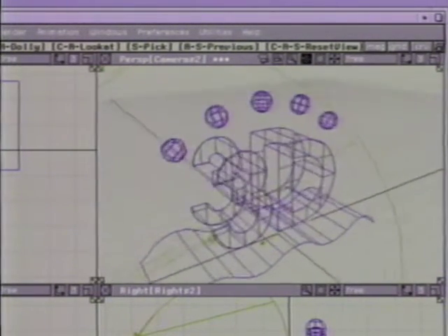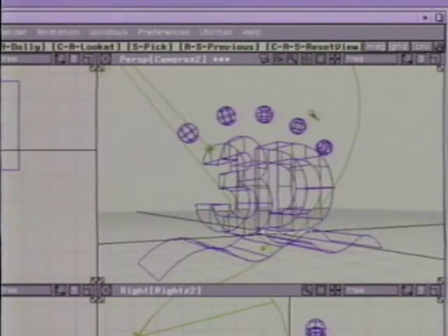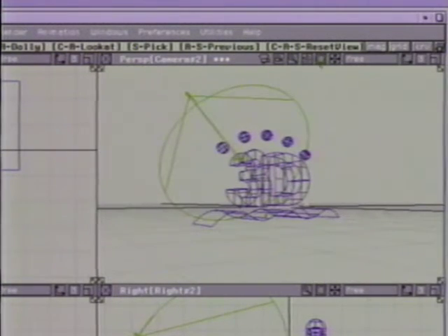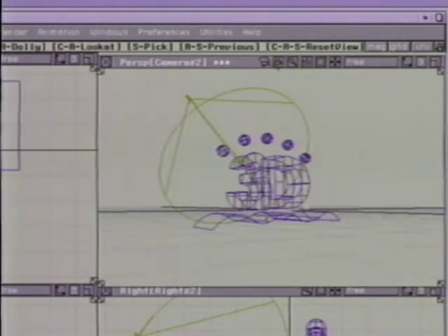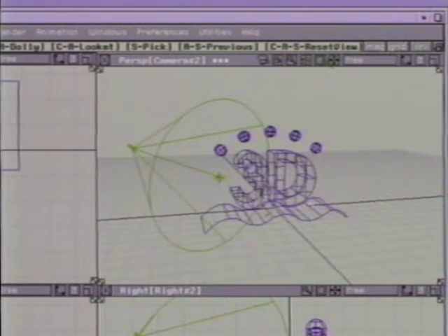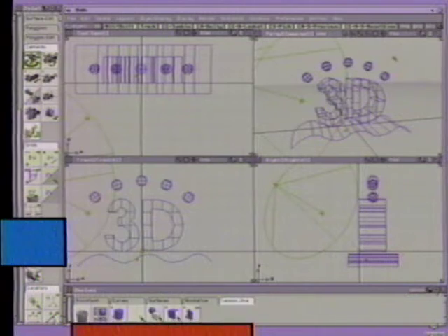For instance, to tumble in the perspective window, click-drag directly on the tumble icon found in the window's title bar. Next, click-drag on the dolly view icon to dolly in and out of the scene. You can use the tumble, dolly, and track icons to get the various views in the perspective window or in the orthographic windows. The three mouse buttons can be used as you work with the view icons to constrain your views.